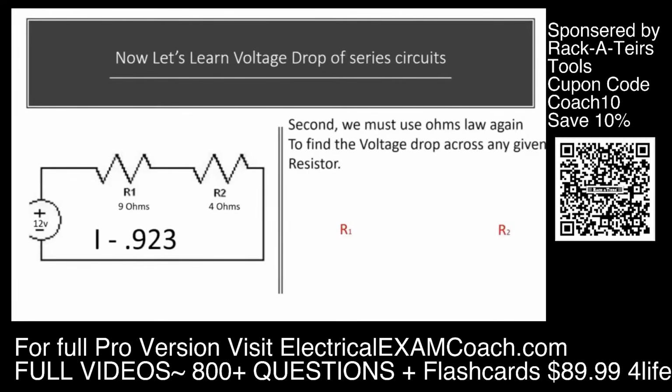Second, we must use Ohm's law again to find the voltage drop across any given resistor. The voltage drop of resistor 1 is going to be equal to R1 multiplied by I, and the voltage drop of resistor 2 is going to be equal to that resistor multiplied by I. Because remember, we're just trying to find the voltage drop. So E equals IR. Just plug in the knowns. In this case, we know the I and we know the resistance, and we're looking for the voltage drop. So we just multiply those two together.